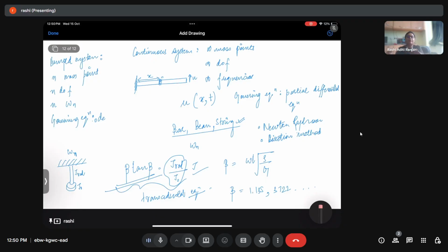Now for example, if I have three directions x, y, z, and I have constraint in the x and y direction, but in the z direction I don't have that much constraint about the movement. So I will look into the mode shapes and I will try to give it frequencies that are not going to cause any trouble in the x and y direction, while for the z direction I will not be concerned because there is no constraint or limitation about the maximum amplitude of vibration. But then it is also important that it does not cause any kind of catastrophic failure in the system.